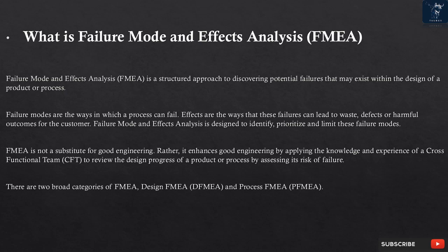Failure modes are the ways in which a process can fail. Effects are the ways that these failures can lead to waste, defects, or harmful outcomes for the customer. Failure Mode and Effects Analysis is designed to identify, prioritize, and limit these failure modes. FMEA is not a substitute for good engineering. Rather, it enhances good engineering by applying the knowledge and experience of a cross-functional team, CFT, to review the design progress of a product or process by assessing its risk of failure.